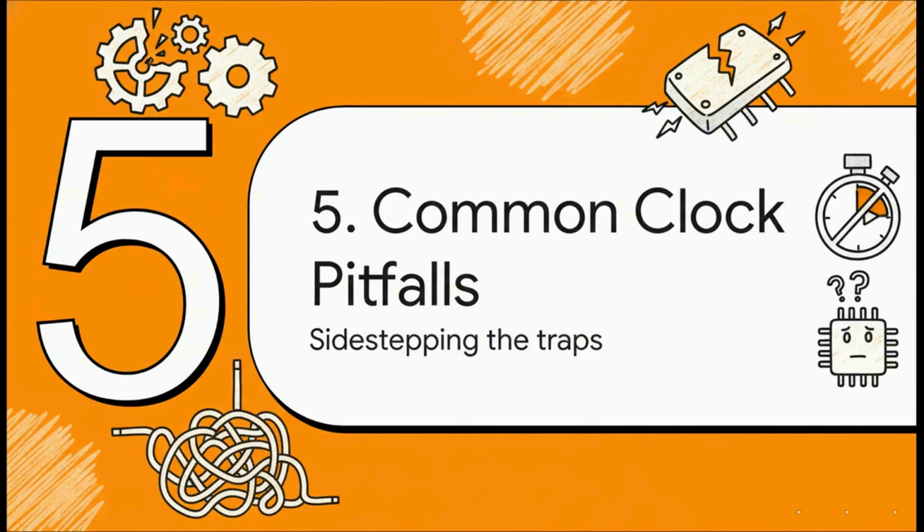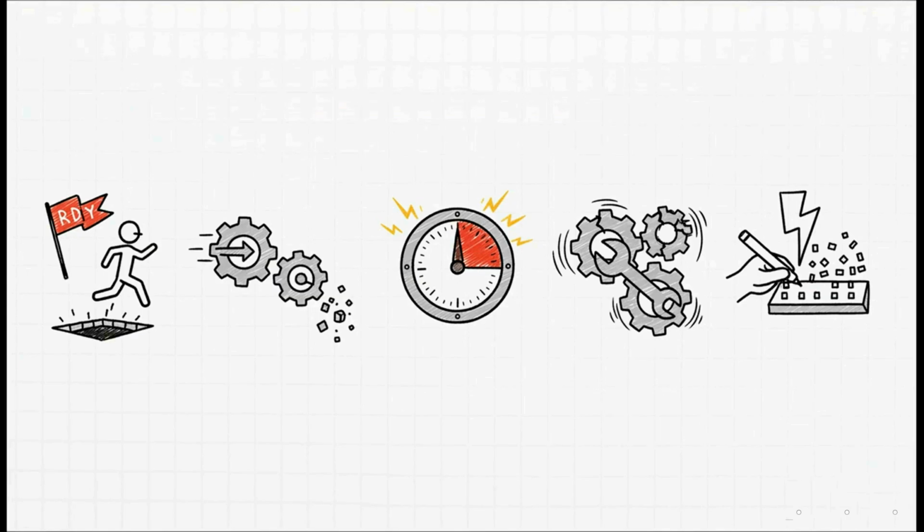You know, getting the sequence right is half the battle. The other half is avoiding the common traps that trip up so many people. Getting caught in one of these can mean hours of pulling your hair out, so let's go over them. Now, we've hit on a few of these already, but trust me, they're worth saying again because they cause so much grief. Number one, hands down, is not waiting for those HSERDY or PLLRDY flags. Right behind it is getting the flash latency wrong. That's a guaranteed hard fault. After that, you've got to check your math and make sure your internal PLL frequency is within the valid range. And remember, you can't reconfigure a running PLL. Finally, a subtle one. Always modify registers in a single atomic operation to prevent weird issues with interrupts.